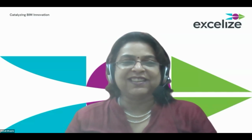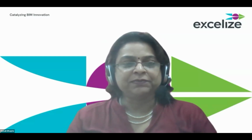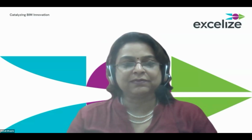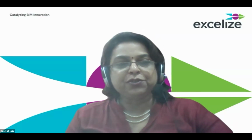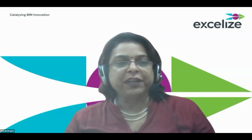Excuse me. Yes. Bhavna has asked a question: when is the right time to start the BIM modeling? Because in India, your concepts change till the last moment. Your schematic also changes many times. So what is the right time to start? If you are a designer, start at schematic concept, any stage, because any change you make is just going to be faster. Like again, I'm repeating it maybe, but in 2D you don't have to change things manually every time because of one change.